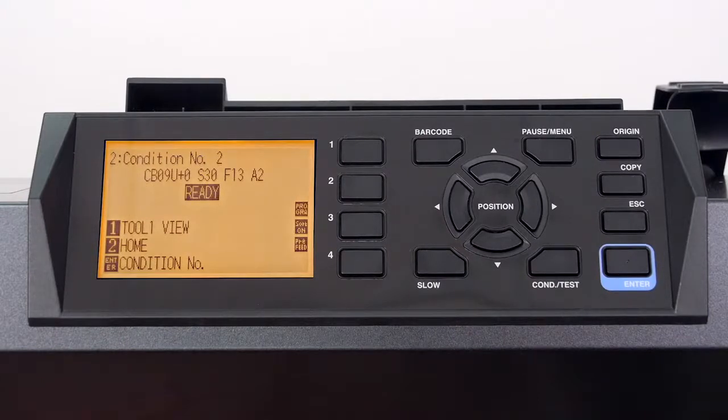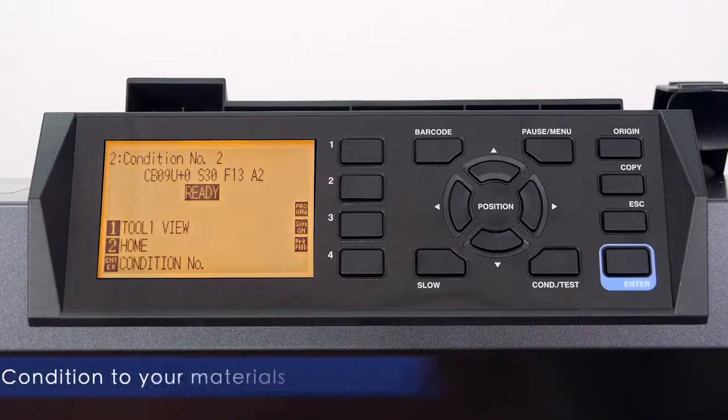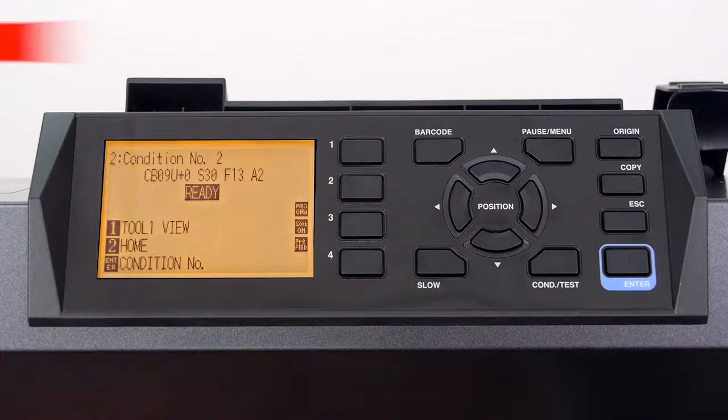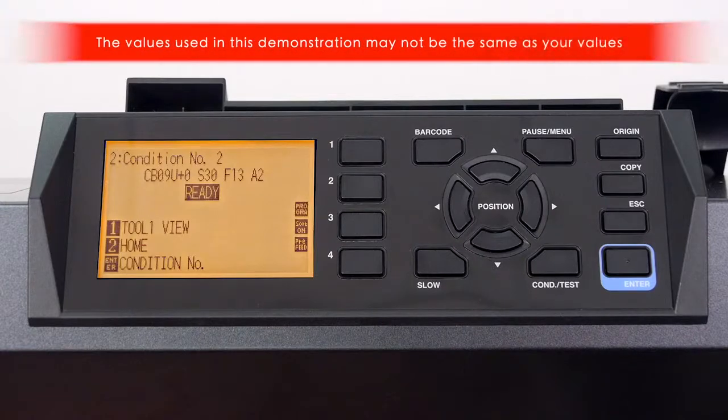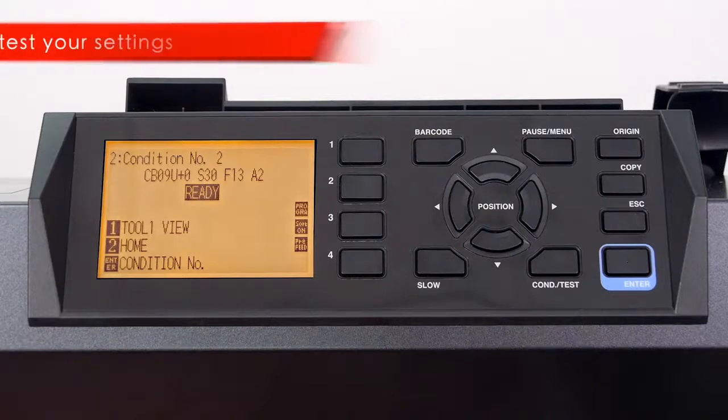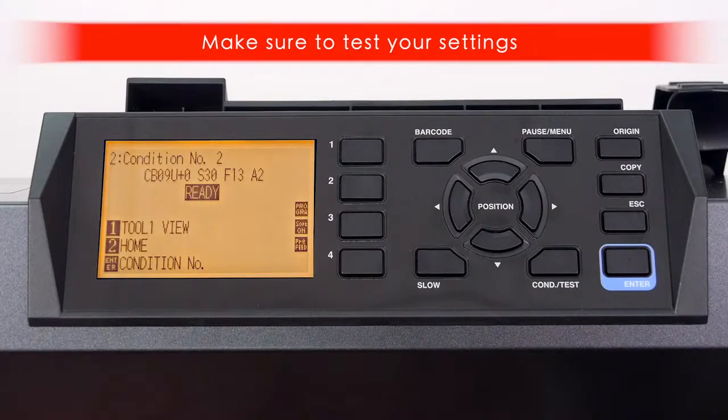Now that you know how to set up conditions, you may want to configure the conditions to the materials you plan to cut or plot. Also, keep in mind that the values used in this demonstration might be different than the values you will use. For instance, your force and speed may be completely different for what we are using here. So make sure to test out the settings for yourself to make sure they are correct for the media you are using.